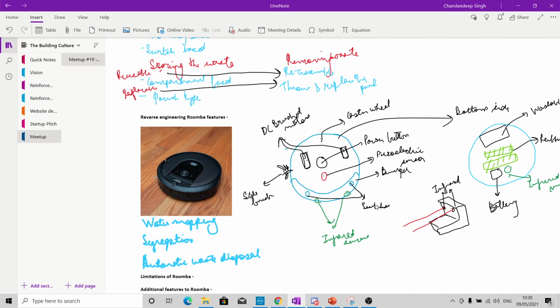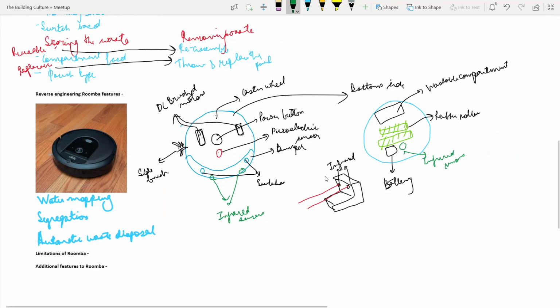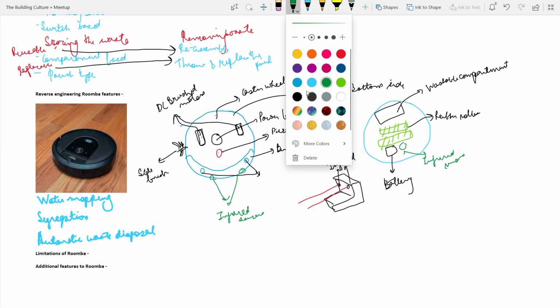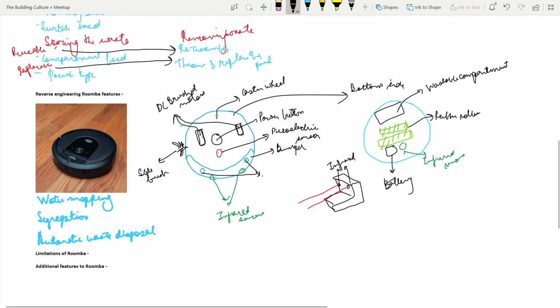I wrote it as switches. So these are actually proximity sensors, right? Yeah, proximity is better because there's no mechanical contact. Switches will be a problem, because if you press a switch in one particular way, it will press better, the other way it will not, so it's not reliable. Mechanical also needs good tolerance so it actually presses. Exactly, so this is a risky thing.